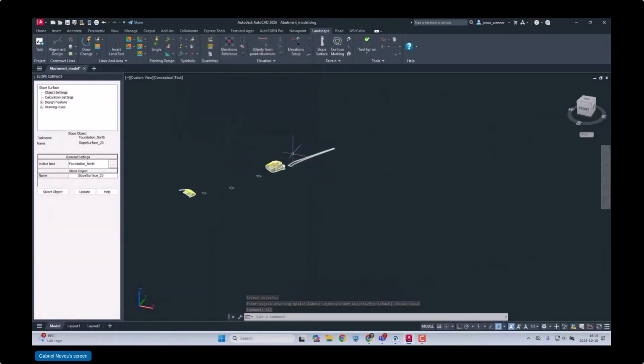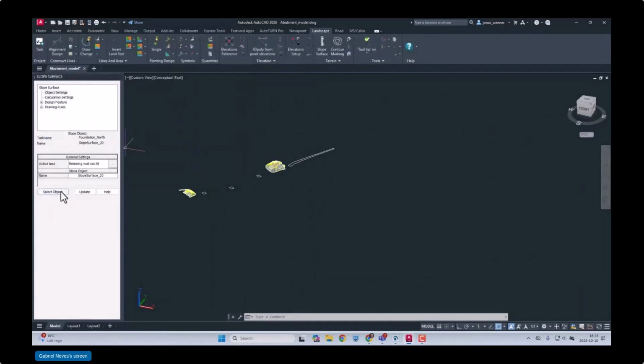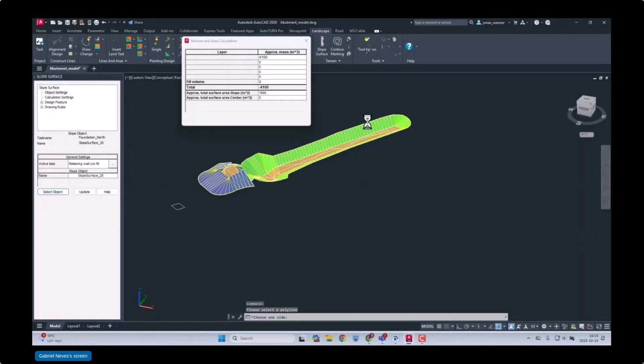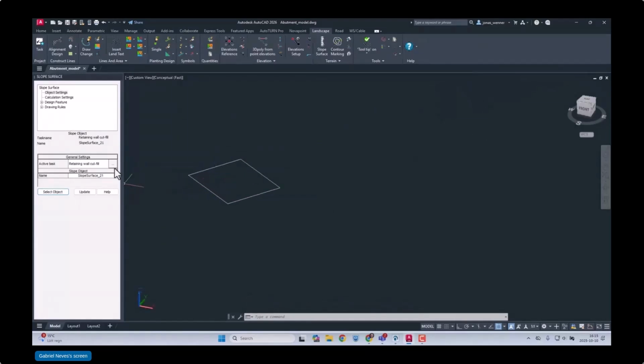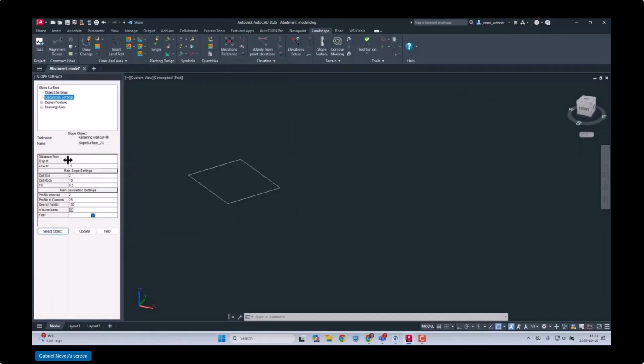So I do this here both for the retaining wall, and we do it for the columns of the bridge as well. And you see also that it creates this 3D model of the excavation, which we can then export from Quadri as stakeout data, for example, to the machinery on site when we should make this construction.